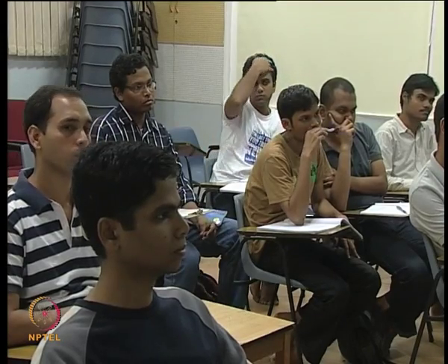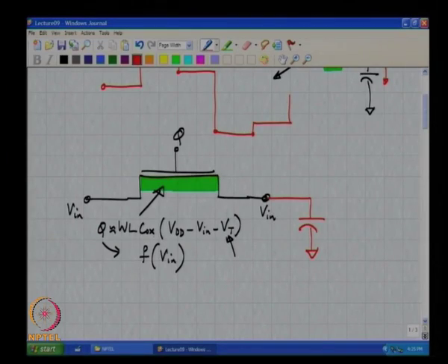Okay. So, without doing any more complicated calculations, it is at this point impossible to figure out how much of the charge went towards the left and how much went towards the right. You understand? Because it must clearly depend on the nature of the impedances on the left side and the right side. You understand? So, there was some nonlinear amount of channel charge when the switch was conducting. When the switch was conducting, of course, just before it was turned off, the voltage across the whole capacitor was Vin.